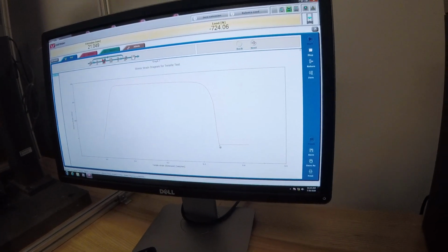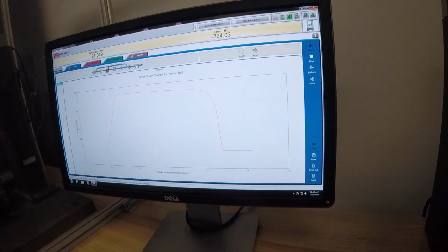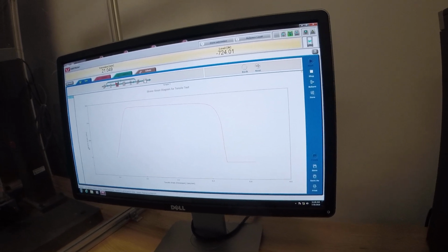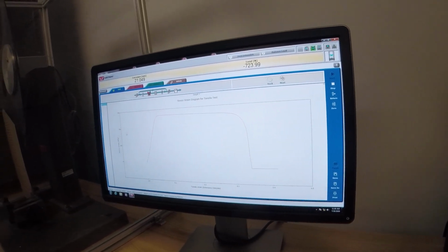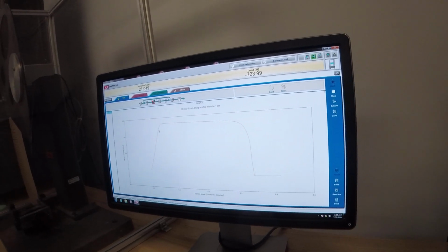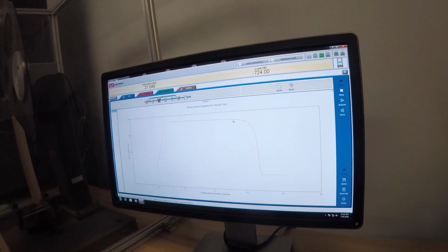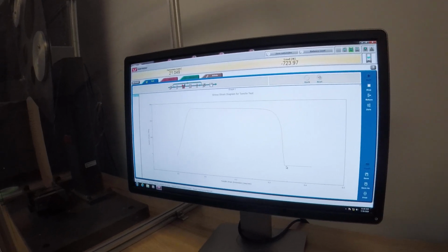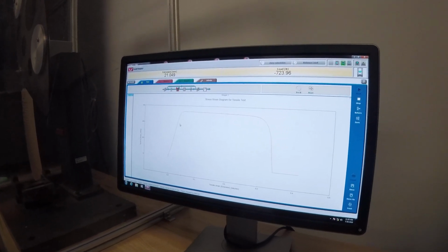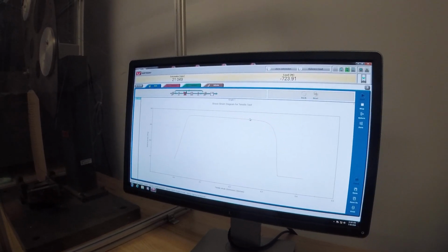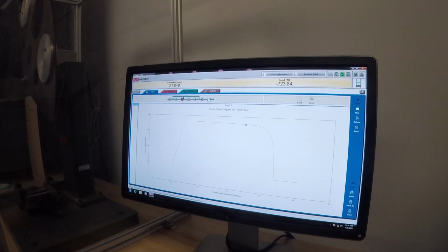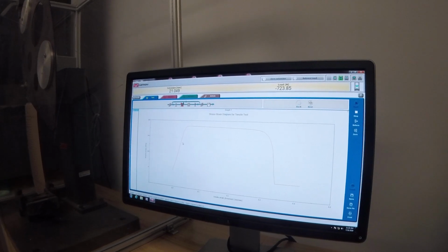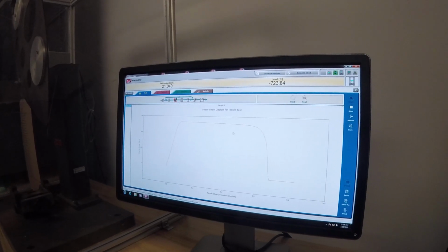And the load also, we can get it based on the tensile strength that we have. This is strength in MPa, and this is strain, no unit for strain. This is elastic region. At some point plastic starts, then necking and breaking happen here. As you can see, we have a very big plastic region because we are talking about copper. Copper is a ductile material, so that's going to have a bigger plastic and permanent deformation.